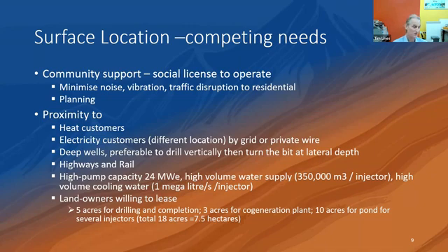And if you're fracking, which we are, and I know you're not, just to let you know, the amounts of power you draw from the existing system or generate yourself are very high, maybe 24 megawatts electric. And we're looking at storing around 350,000 cubic meters of water for every injector. And for cooling, in your case, I think you're probably going to cool with air source, in other words, fans, while the equivalent cooling for us is about a megaliter per second. So they are very substantial utilities that you have to think about when it comes to putting together your field development plan.